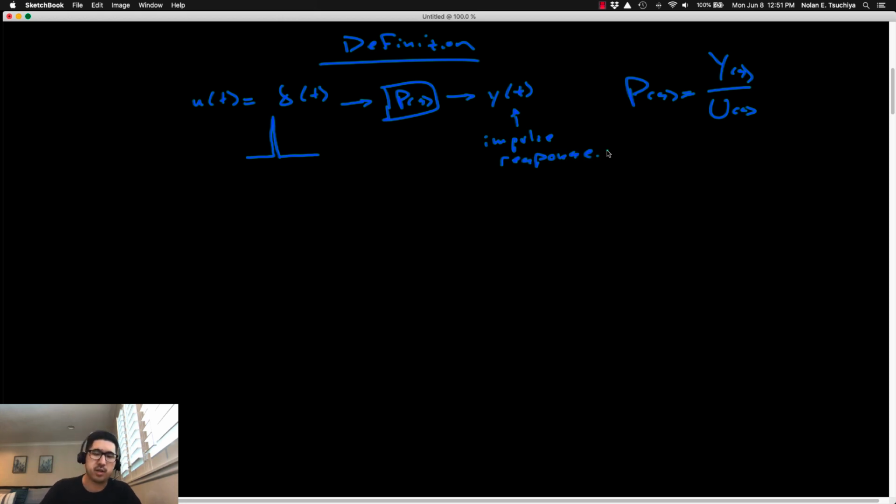And our definition of stability depends on the impulse response. The reason we use the impulse response to define stability is that what you're doing with an impulse is giving the system some initial amount of energy by hitting it with a ping or a hammer, and then you're not interacting with the system anymore. So you're letting the natural system dynamics propagate after that initial burst of energy. That's why the impulse response is a good way to define stability.